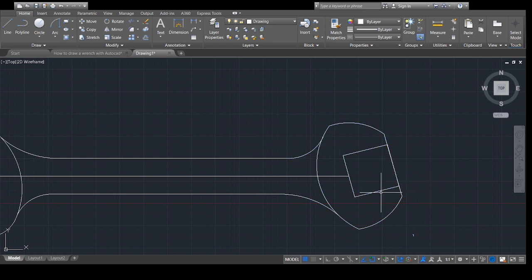Okay, so then the other fillet, the last fillet, to remove these corners, radius 16, enter, select the first object, that you can see the corners become smooth.